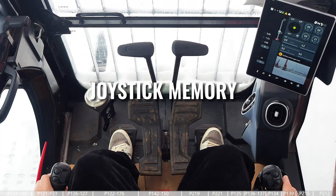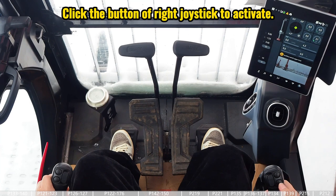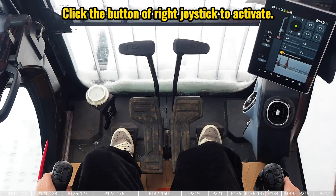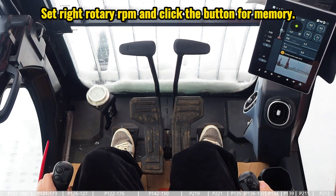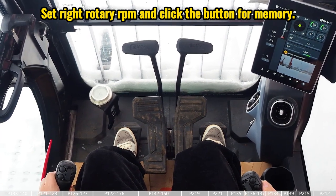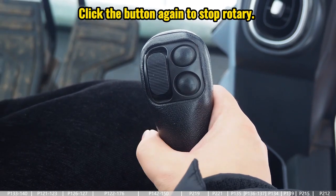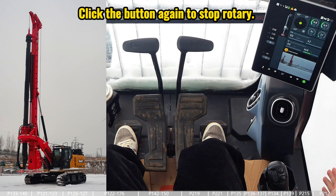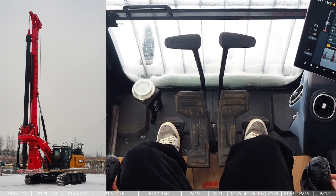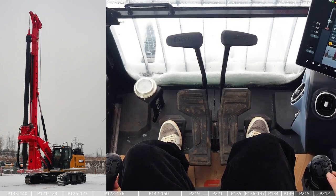Alright, in this video, we're going to talk about the memory function. The memory function can be activated by this button at the right joystick. During the drilling, if we already start the rotating of the rotary and we set it to the right RPM, then what we need to do is just click once on this button. And then we can release the joystick, and the rotary will keep rotating at this RPM. And if we want to stop this function, we just click once again, and the rotary will be stopped.